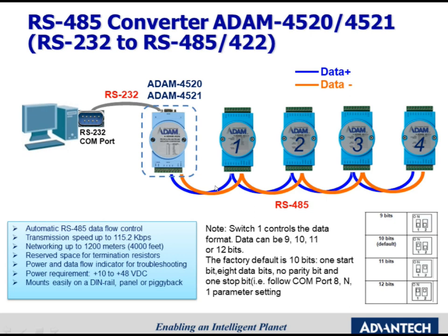First one is the RS232 to RS485 converter, and it's called Advantech 4520. As you can see, there is a converter between the RS485 device and your PC.